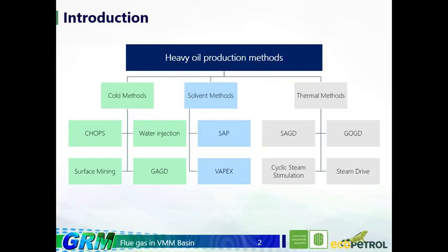About the solvent methods, they could be the ASP or the VAPEX. ASP uses surfactant, alkali, and polymer to make changes to the fluids in the reservoir, and VAPEX uses solvent in the process. The thermal methods inject energy, thermal energy, into the formation,